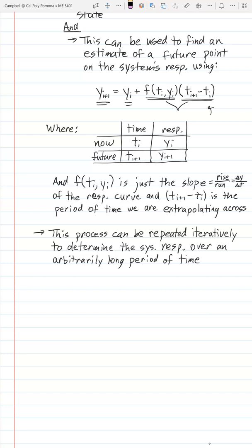And based on our understanding of how reliable our propagation methodology was, we would understand that we're starting to get some errors creeping in, and so then we need to repeat that orbit determination process again within T period of time, to ensure that we could continue to propagate that orbit properly.